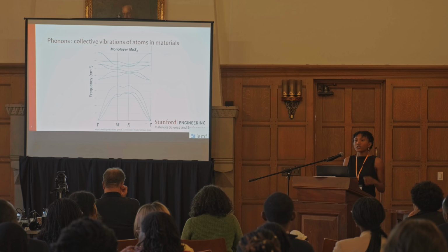We do this for all of our nano-wrinkled samples, and we measure a reduction in both the in-plane and the out-of-plane thermal conductivity of about 50% for the samples with wrinkles in them. We believe that this happens because, as I said before, what we observed is a decrease in the phonon mode frequencies in these deformed samples. This also leads to a decrease in the group velocities, or the speed of phonons moving in the sample, which will impact and lower the thermal conductivity in plane.